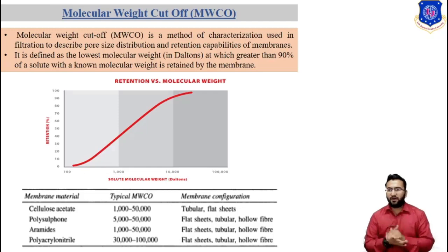Typically, a mixture of water-soluble molecules and macromolecules is made and presented as the feed to the membrane. For dialysis, reverse osmosis and nanofiltration, the mixture will typically contain mono and divalent salts, urea, sucrose and alcohol. For ultrafiltration and microfiltration membranes, the macromolecule solution can be a mixture of proteins or a polydispersed solution of a single hydrophilic polymer such as dextran or polyethylene glycol.